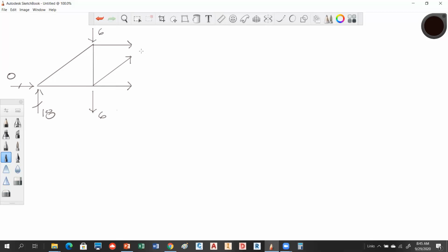But we'll go ahead and label this. This is member BD up here. This is member CD. And this is member CE, okay? So I cut through my section completely. I just modeled them all in tension, brought in all of my forces, and now I'm ready to apply my method of sections. Okay, is everybody okay with that picture? Because that picture is all important. And if the reactions we blew, we're in trouble too, okay?